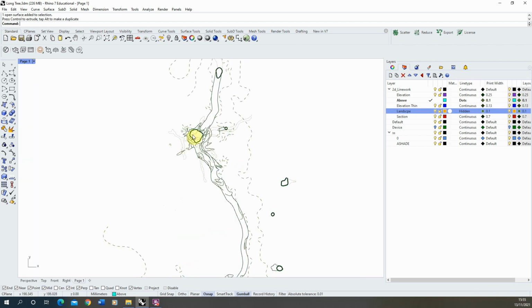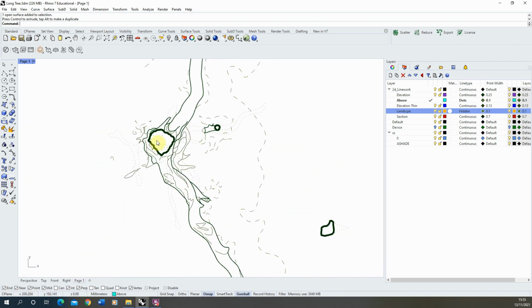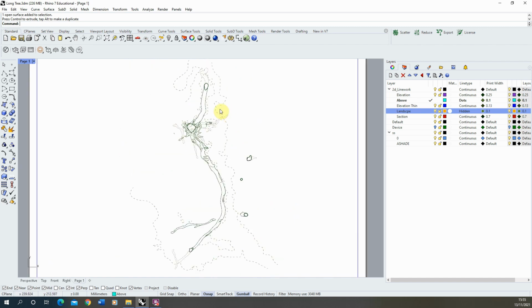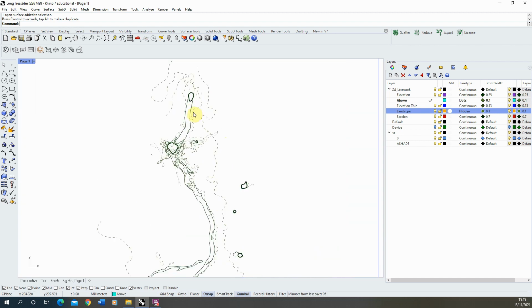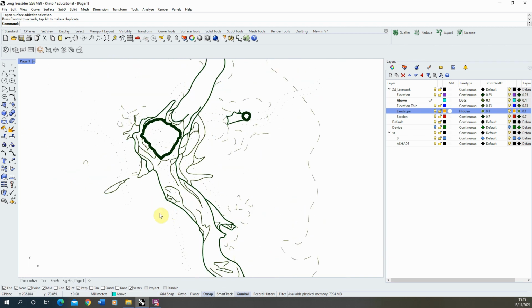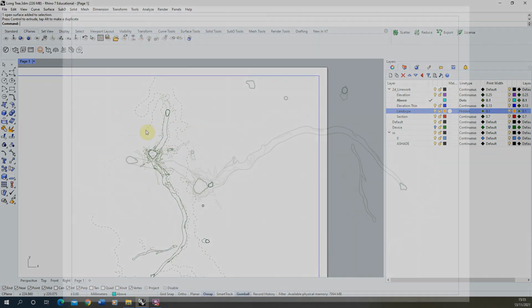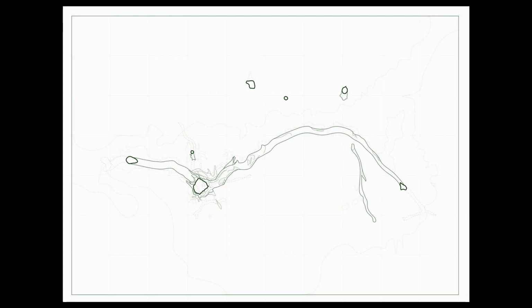And as you can see with my line weights, we've now got our dotted line for our tree above. We've got our thick line for where the tree is being cut. We can see the branches, and then we've got this dashed line to just give a sense of the outline of the terrain. And you could start to add in hatches into this as well to draw more into this plan. We could add in labels to start to detail some of the textures. You might want to go in and add more to the texture of this piece as well. But that essentially is the base level of this plan drawing that we can start to draw into.